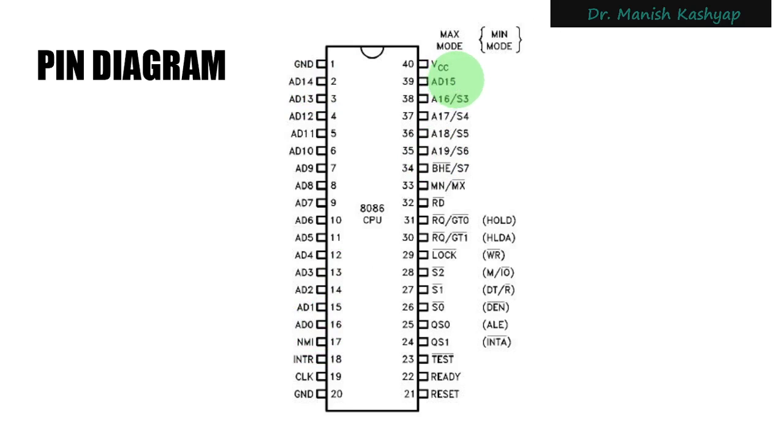So data and address bus are multiplexed, and the lower order 16 bits of the address bus are treated as the data bus. So these addresses will be floated in the T1 clock cycle. Probably you have known the meaning of T1 clock cycle from our earlier discussions, so that's why I'm using this terminology. From the T1 clock cycle, the addresses will be floated onto these, and in subsequent clock cycles, you will have data which will be floated onto these, right?